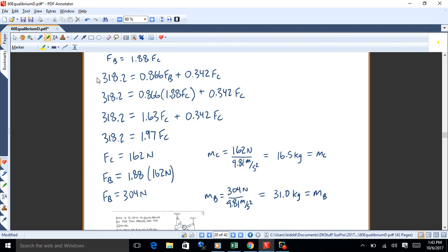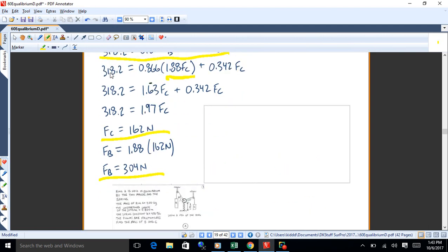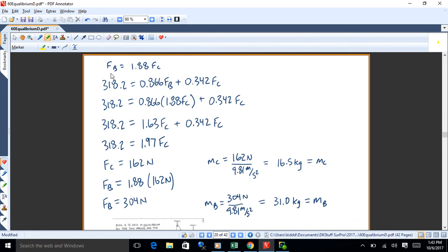Oh, so your first step you did W equals 4 kg times 9.81. So all those values will be negative? Yeah, all the weights, because they're going down. What you put into an equation is based on what direction you assume it acts. So I assume they were down, so it goes in as a negative. What you get out of the equation tells you whether your assumption was correct or not. So, like I assumed it was negative, I solved for it, the answer comes out positive. The meaning of the positive answer was I was right, it does act down. That's kind of how that goes.